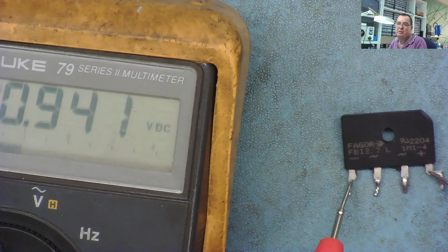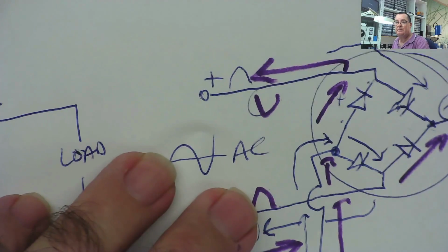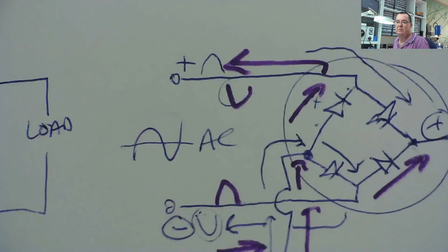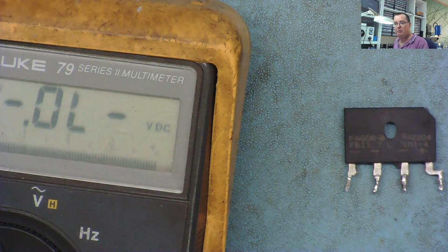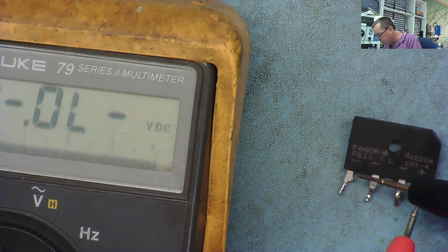And effectively that's because you're coming through two diodes in series if you look at the actual schematic for the bridge rectifier, which I just showed you. I can just find this again. Here's one, here's a diagram. So effectively you're reading through two diodes, that's what it comes down to when you see that. But you only see it when it's effectively back to front, yeah? When the red's the positive you don't see anything. So that's that.